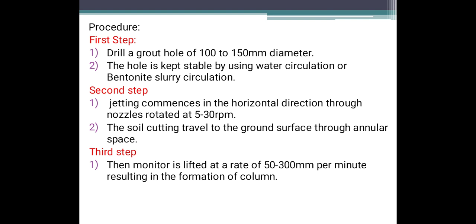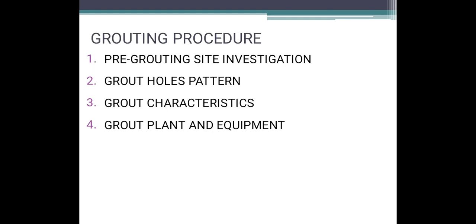Third step, to monitor, then lifting of the drill bit, which is lifted at the rate of 50 to 300 mm per minute, resulting in the formation of the column there.